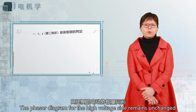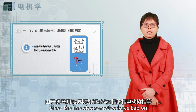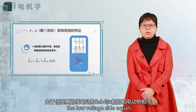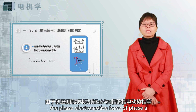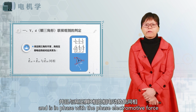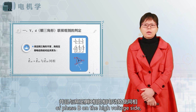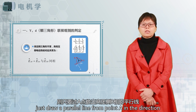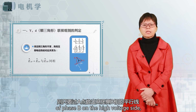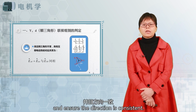The phasor diagram for the high voltage side remains unchanged, since the line electromotive force EAB on the low voltage side equals the phase electromotive force of phase A, and is in phase with the phase electromotive force of phase B on the high voltage side. Just draw a parallel line from point A in the direction of phase B on the high voltage side, and ensure the direction is consistent.